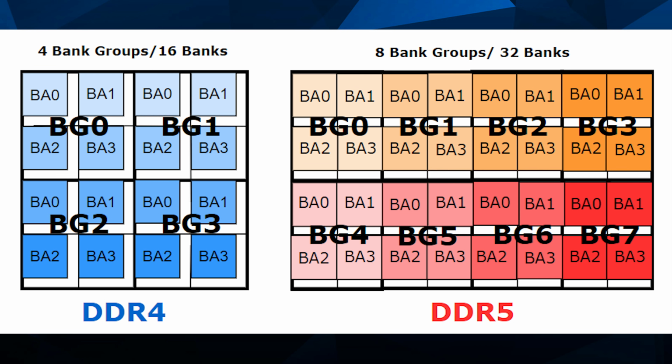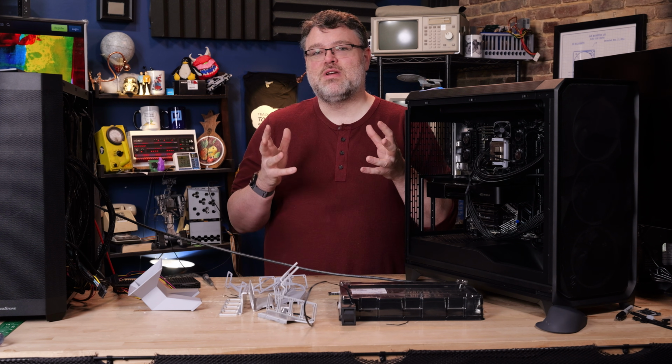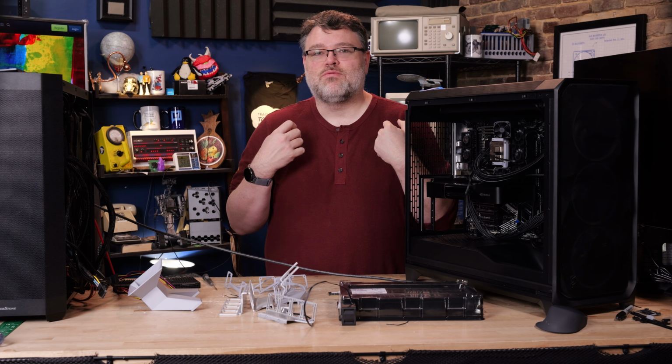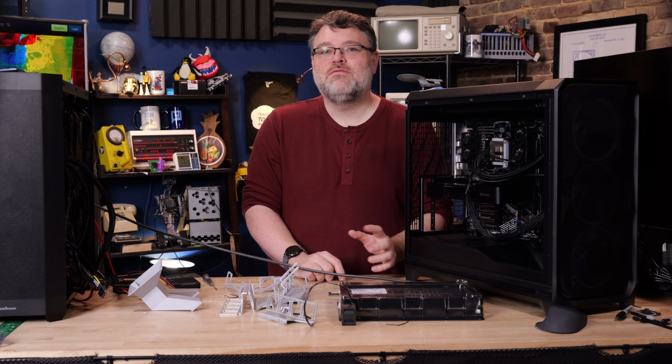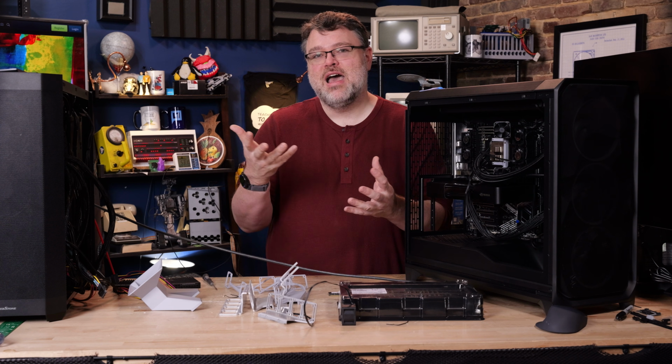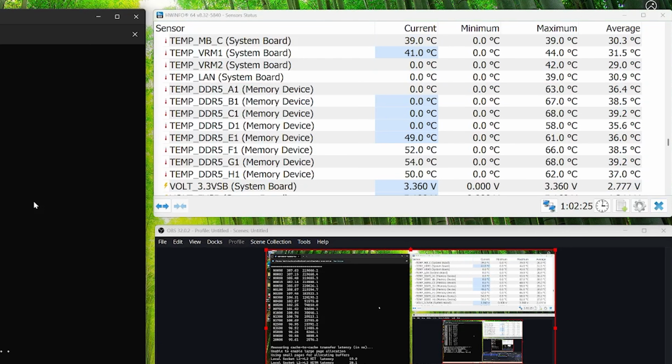There's other reasons. But DDR5 also increases the bank count, bank groups, refresh flexibility, and all of that enables higher speeds, but it also increases the background activity inside the actual memory chips, things like refresh flexibility. See, DRAM loses its contents, the electrons like to leak out. Part of the mechanism here is that the system reads the contents of memory and then writes them back to refresh the contents. That's not new in DDR5, but the timing for that had been very strict, but DDR5's rules have sort of given you some flexibility and things have improved. Of course, that means the chips are driven harder, and more activity means more heat and more power dissipation, 15 watts per DIMM upwards of.